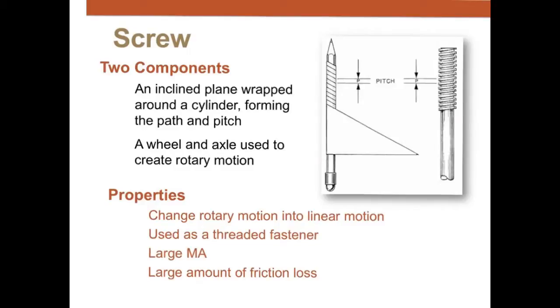Alright, so a screw is going to have a really large mechanical advantage depending on how large the screwdriver or wrench is that you're using. But most of that force, of your force effort, is going to be lost to friction. But if you think about it, you want all of that friction there, because when you're putting a screw into something, you're trying to hold it in place.